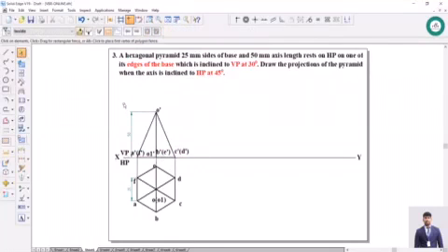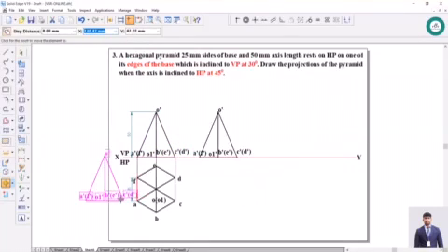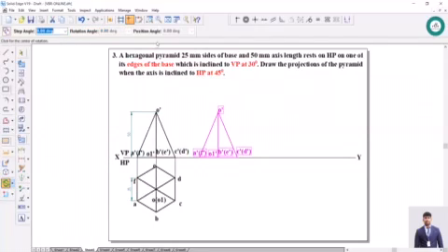Next, select this front view. Go to move command, switch on the copy and ensure you move with an endpoint and place it on the XY line. Next, go to rotate option, click this endpoint and the opposite endpoint.